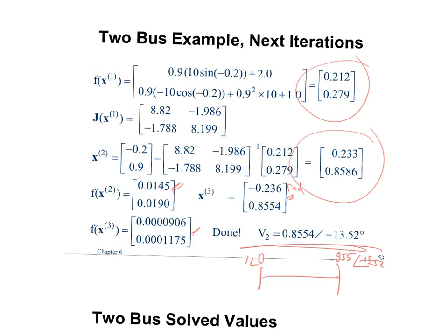Remember how we said real power flows from a higher angle to a lower angle, which is the case, right? We went from whatever power has to be injected at bus 1 because that's the only source of energy, and it's being demanded at bus 2. So we're moving 200 megawatts there. So we change 13 degrees. And the same thing for the magnitude. We have 100 megavars demanded at bus 2. So all the reactive power is going in at bus 1, so its magnitude should be higher than at bus 2, which it is.